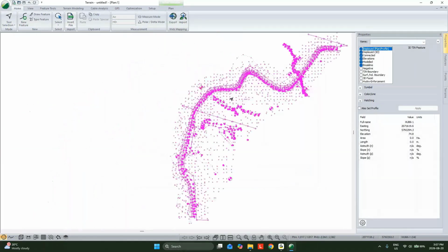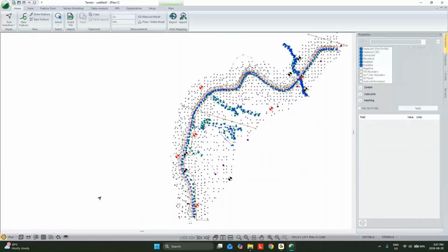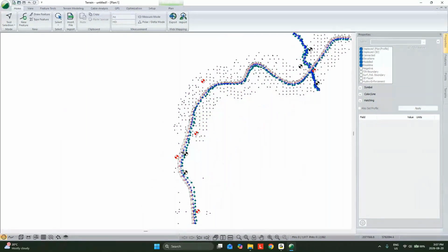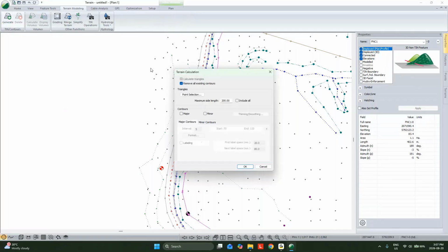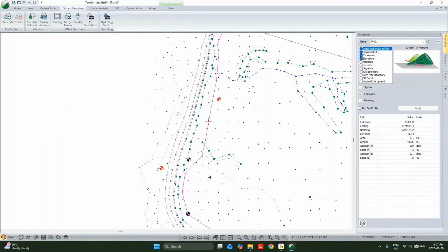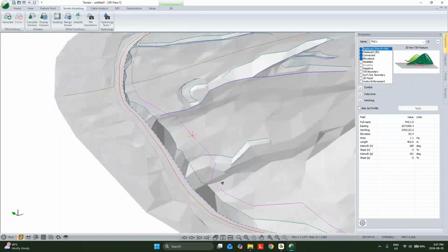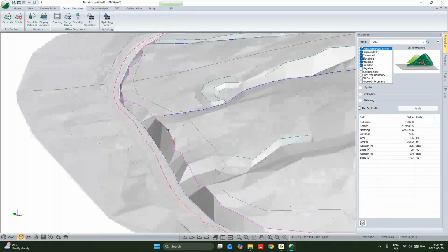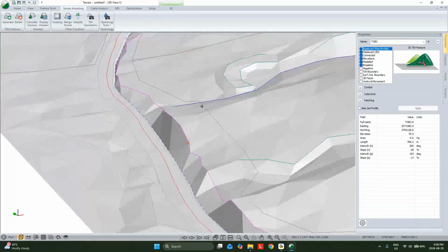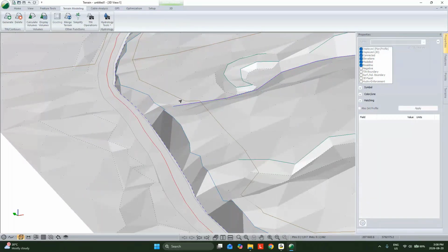And now instead of just having those 3D points, we've got 3D points and lines, and those lines are formatted the way that we like. So again, break lines are break lines. Other lines like this fence line are not even included in the model. So when I take this and I remodel this stuff, we can come in here and we see those break lines make those nice crisp edges, but things that aren't tagged as being in the model are,